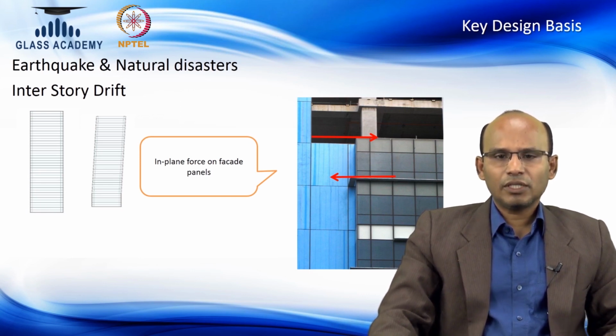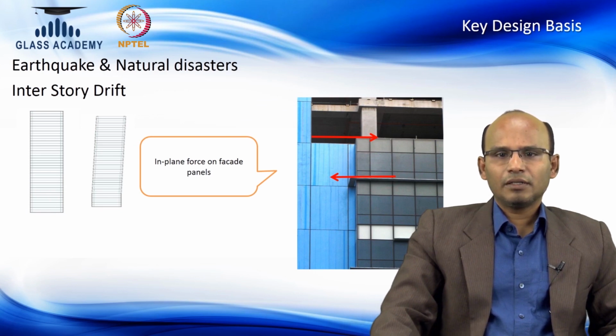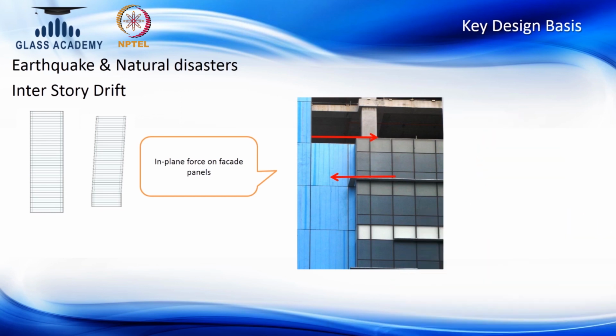As structural engineers should be aware, the facade system or its material is a very strong element in supporting out-of-plane loads like a wind load acting on a plane. It may be weaker in its own plane, on this minor axis loading. So the building sway may impose minor axis loading which needs to be checked during the design.